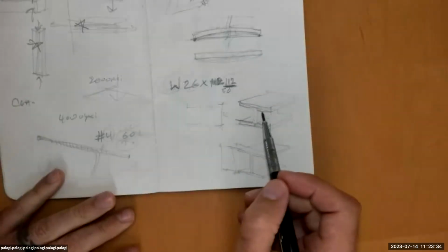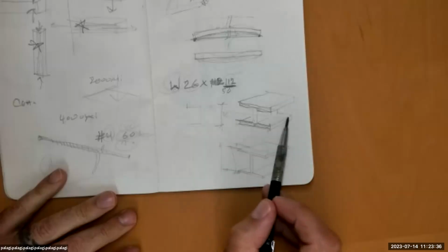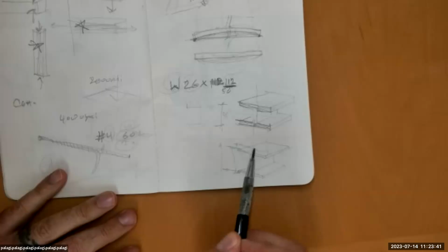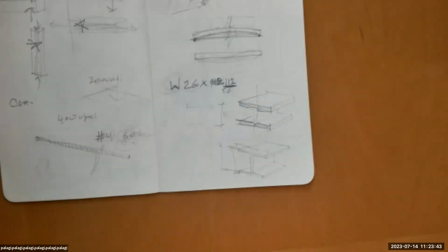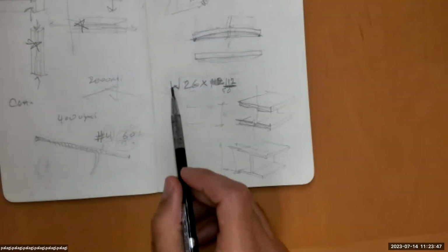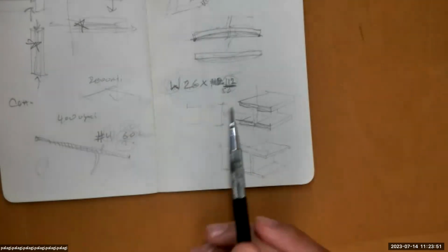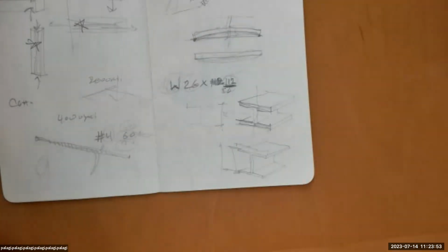This is also why, even when we think of them as columns, the center line, maybe where the wall attaches, none of that needs to change for it to become a stronger member. So this works with all of them, the I's, the C's, the L's. The second number is its weight. It's also a thing where steel is sold by the pound.